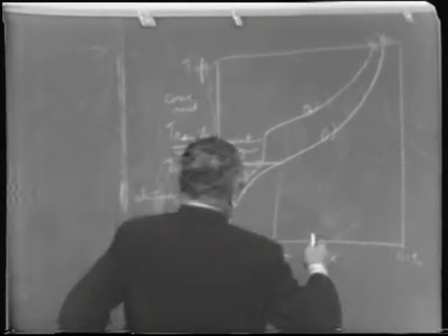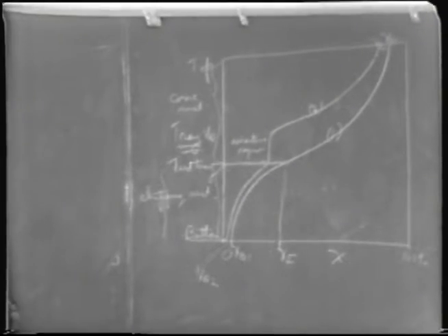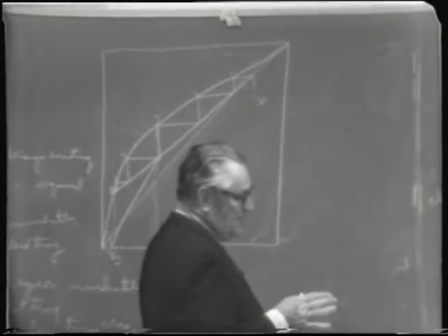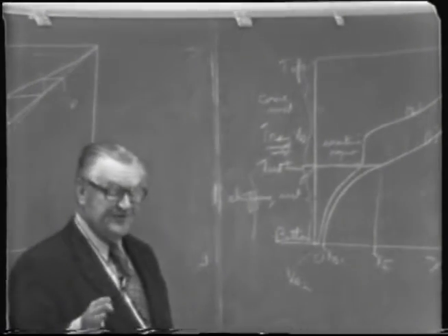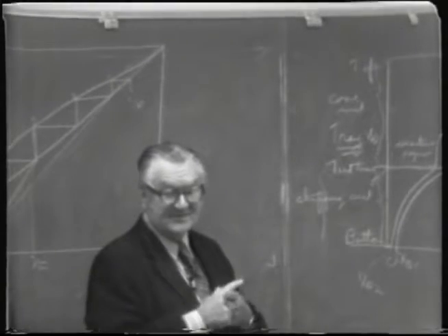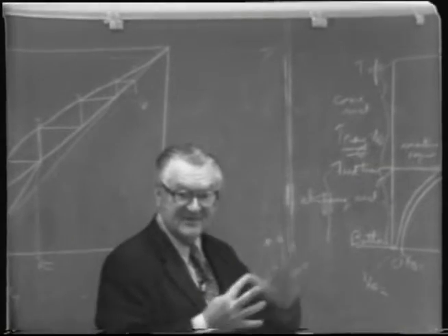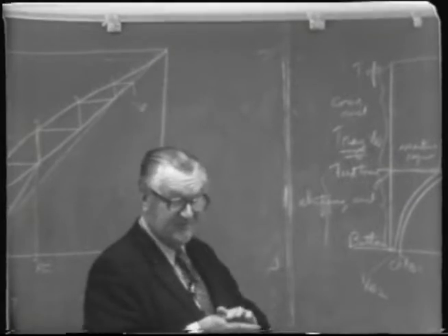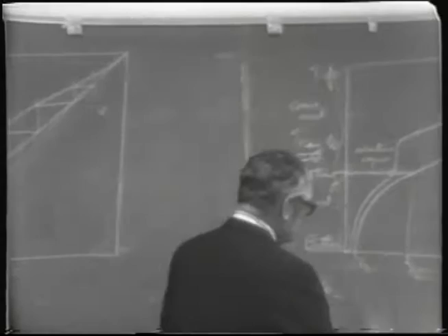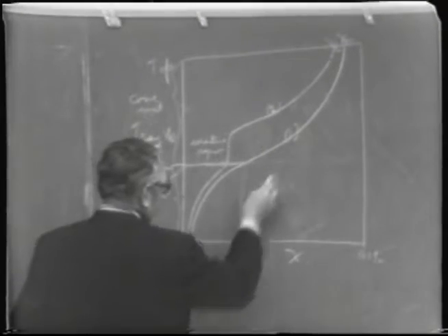Then we can have the reverse situation where the concentration of alcohol or the volatile component on the feed tray is somewhat larger than the feed. Again, we're getting an inverse action somewhere in the column because we're mixing streams of two different concentrations, an inverse effect of what we're trying to do, which is separate. And then you get an inactive region down below here.